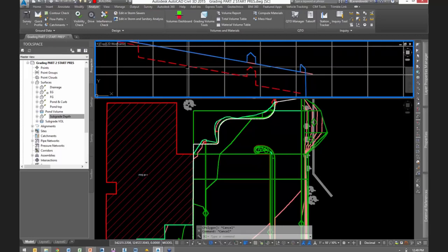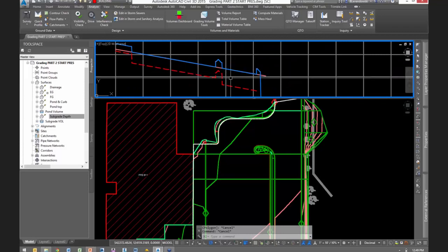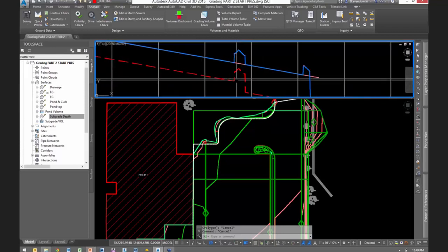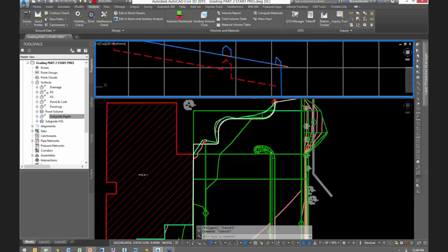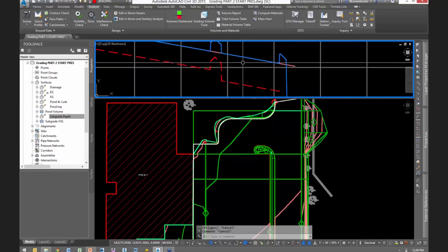The red line is my subgrade surface. And now you can see there's that 1.5 feet, there's that foot depth, and there's the 8-inch depth. Now the limits of some of those subgrade depth polylines can be adjusted depending on how you're excavating around these large curb islands and such. But the idea is that we can link this stuff together and make it all dynamic.